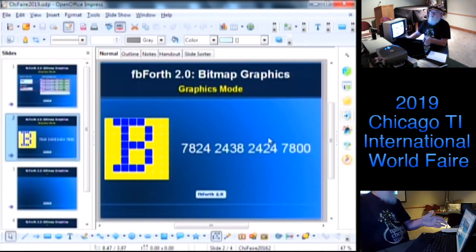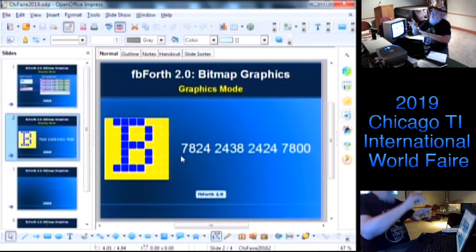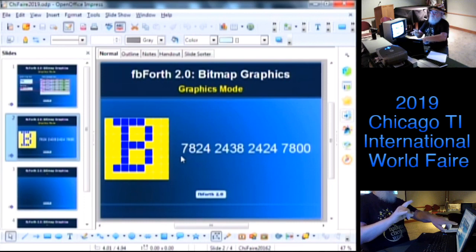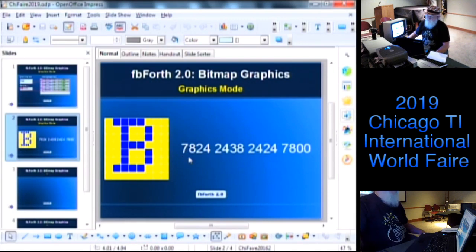The left side is all you have for a character from here to here. Well, you have a space for 2 characters, but it's 4 bits by 8, and then this half 4 bits by 8. So in order to set a line of characters, every other character has to be shifted by 4 bits. The first time you're writing to the leftmost side, and the second time you have to shift it to the right side, and it gets to be a little difficult to think about.